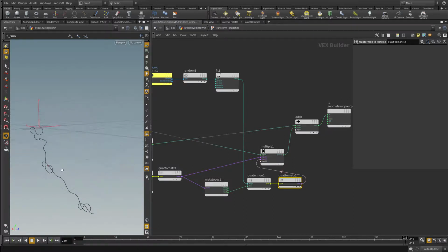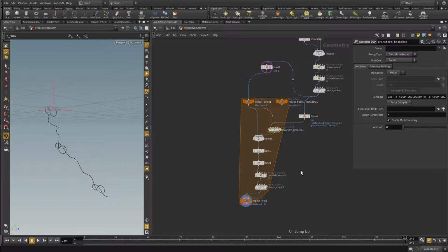And you see everything looks different now. And that is due to the fact that a second rotation is applied whenever a new primitive is appended. And if I go up and choose another value for this rand rotation, every piece is rotated differently with a random value. But at the moment, it's not random per segment, because this value is global. We have to alter this value for every iteration.